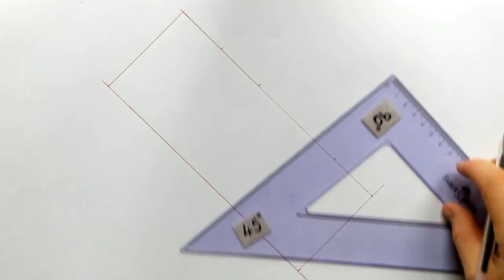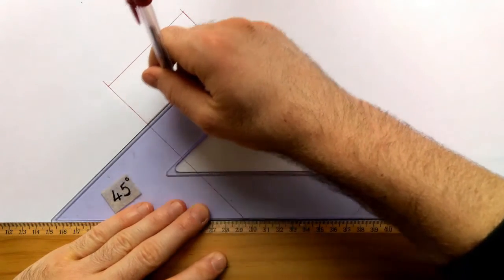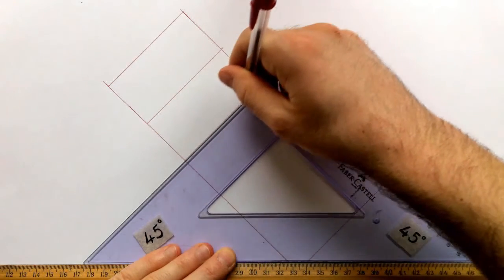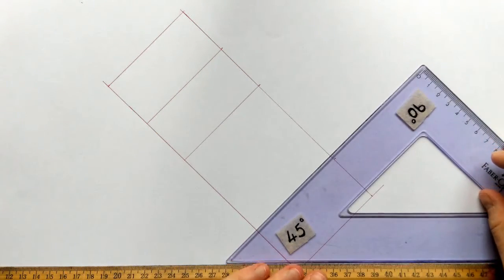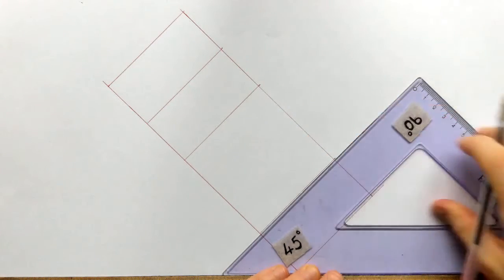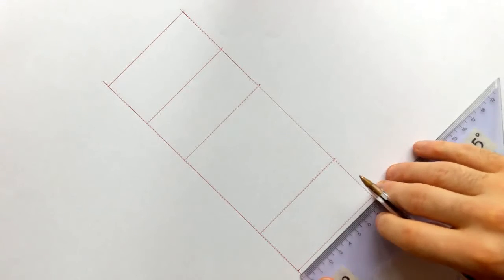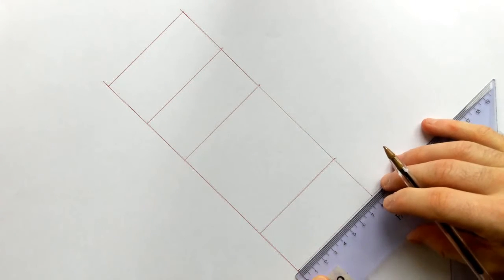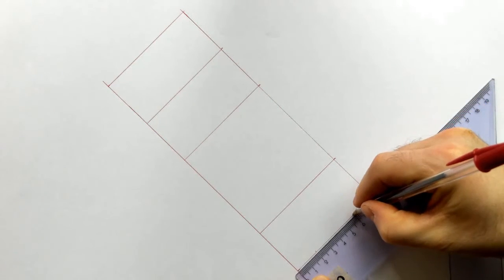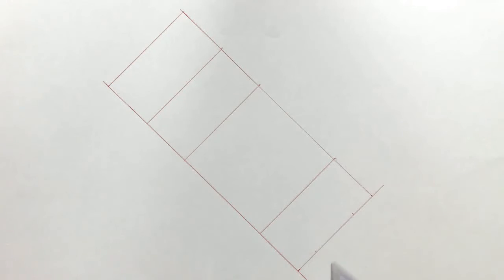Happy with that. All of those lines project down at 45 degrees, so I'll put them in as construction lines at this moment in time. And same with this one, yep. Also at the bottom here, I know that this measurement measures in 20 millimeters, and then it also measures back 20 millimeters. So I'll mark them in, and that'll help me locate some other further points.